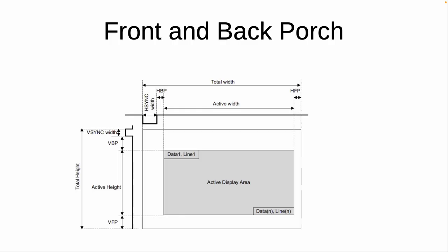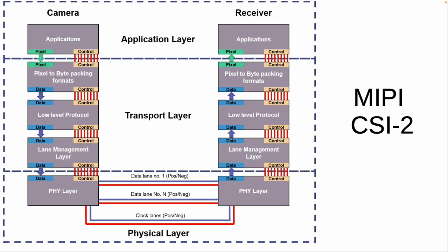So there's an image area and there's some time delay between, which basically gives the beam some time to come back. And so DVI is very well defined. There are certain dimensions you can use, and they have certain display and front porch and back porch sizes, and there are online calculators that tell you exactly how all of this stuff works.